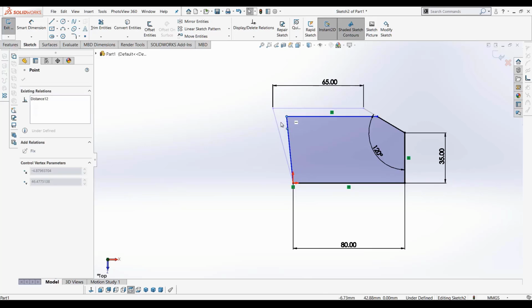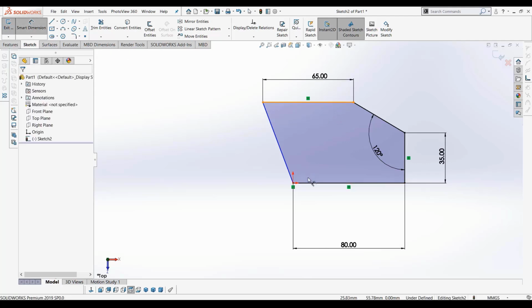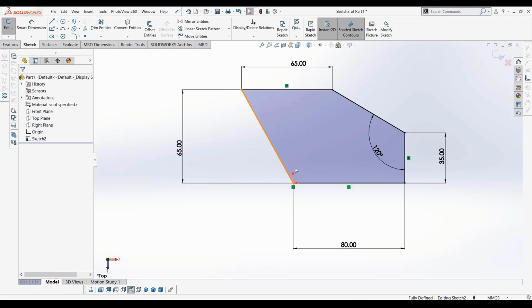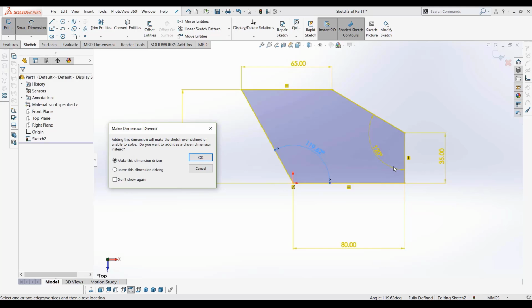Now let's see what component is missing. The height here is definitely still not specified. So we say the distance from here to here should also be 65. I don't need to give this an angle, because all its components are complete. This is a rule of geometry. When we draw such a shape with this size and this angle, I can no longer assign an angle to this size. For example, I say the angle from this to this should be.